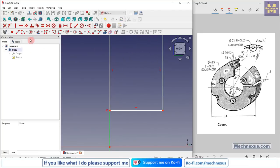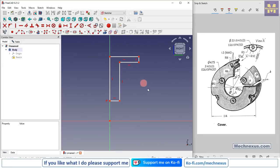create a rectangle, and now select line tool and create a horizontal and vertical line, and trim out the unnecessary geometry. So here what we are doing, we are creating this profile on a right plane, and then we will revolve it around the axis. So let's constrain the dimensions.